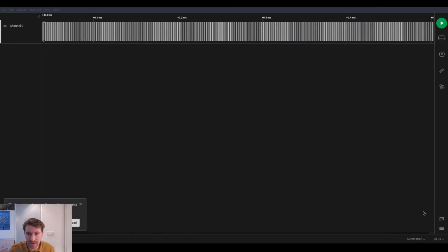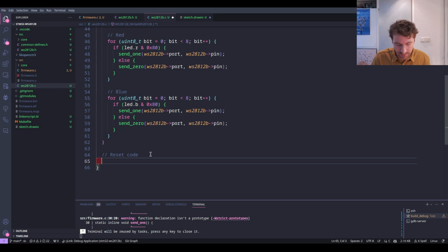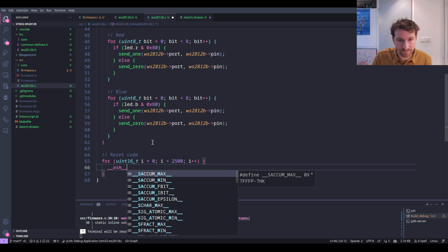All right, so in order to do this, we're going to have a for loop, and we're going to run for some number of iterations. And the number of iterations, well, if we think that roughly 2 no-op instructions is 20 nanoseconds, then we need 50,000 divided by 20, which is like 2,500. So if i is less than 2,500, keep going, and we will just insert some.